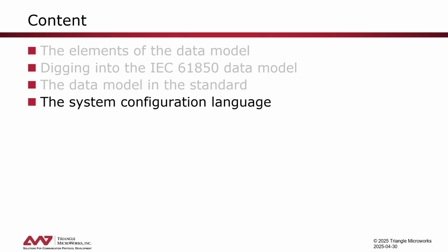once the enable is active, what we will see communicated from that data object as status value will be the substituted information, and at the same time in the validity we will indicate now that data is not from the source anymore, but it's now from the substitution. The source is not anymore from the process, but it's now from the substitution.